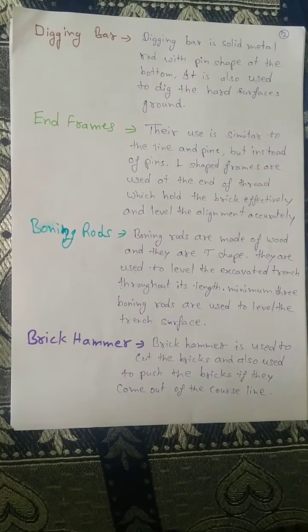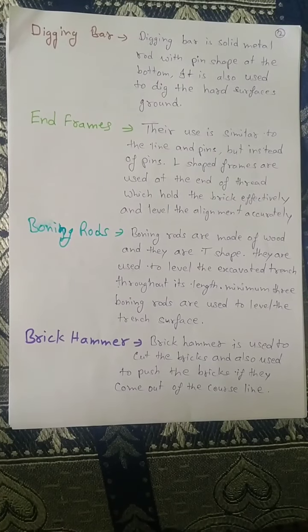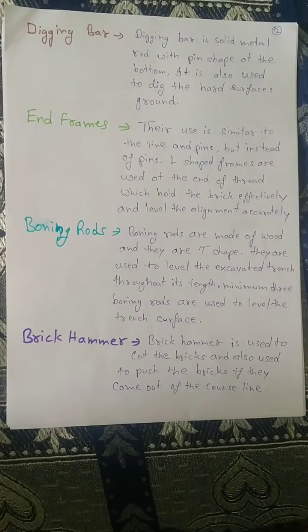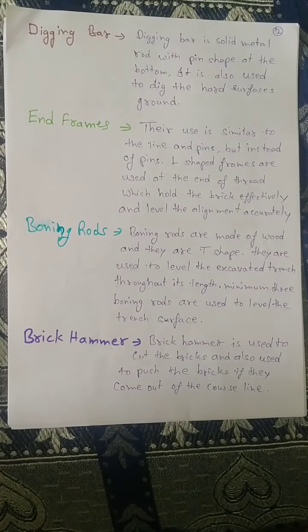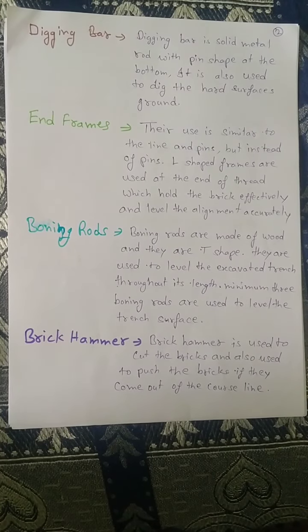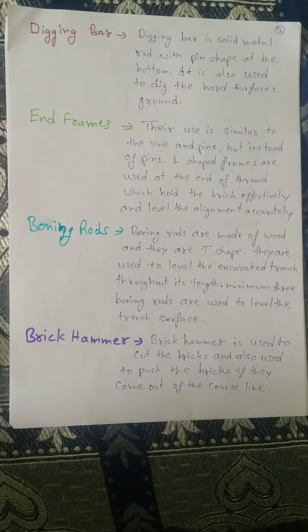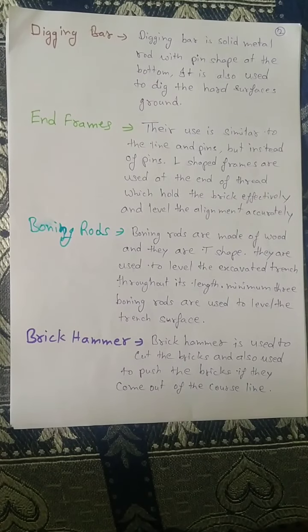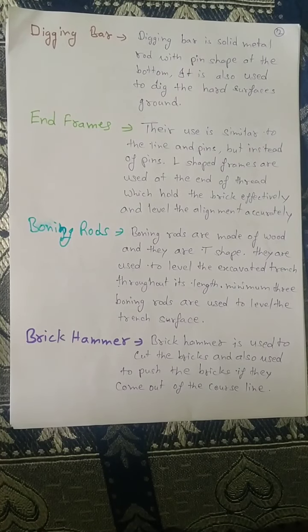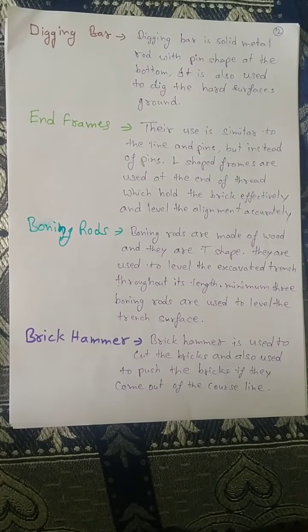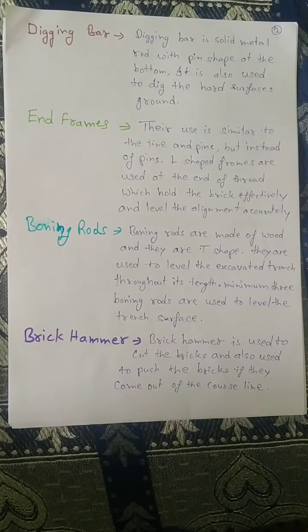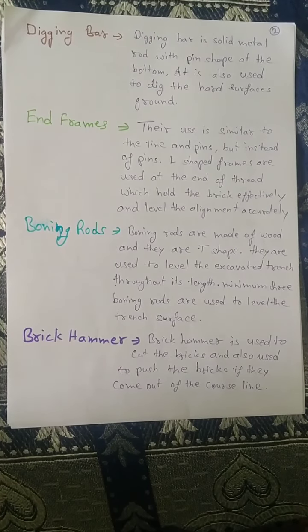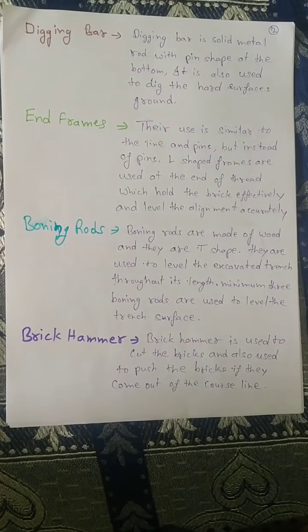Boning rods. Boning rods are made of wood and they are T-shape. They are used to level the excavated trench throughout its length. Minimum 3 boning rods are used to level the trench surface.